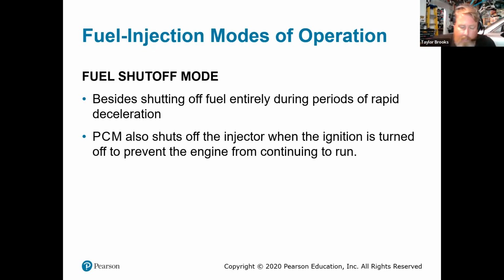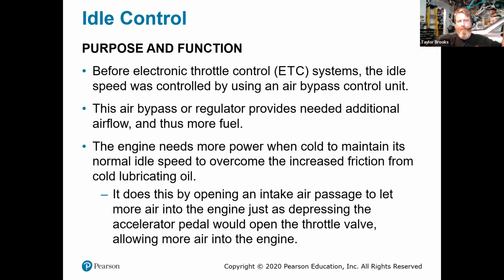Usually when we shut off an engine, we'll shut off the fuel pump and shut off the injectors, and that stops the combustion process from happening. We'll usually leave spark on for 1 or 2 milliseconds prior to shutting the engine off, just so that we can burn off any additional junk that might be floating around in the cylinder. And it keeps the fuel injectors off until the engine goes back into the operating state.